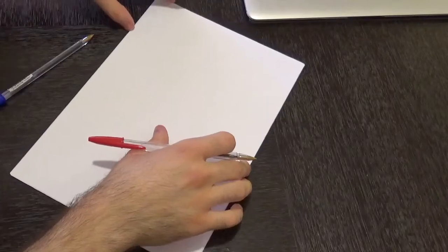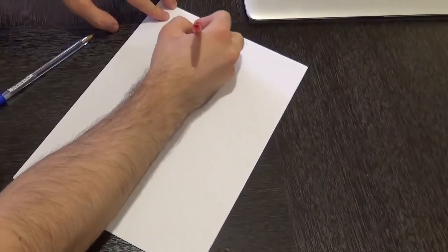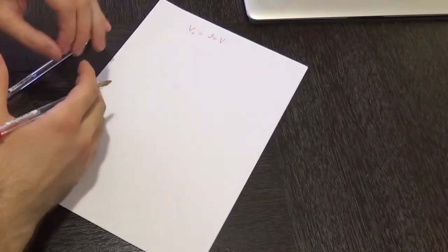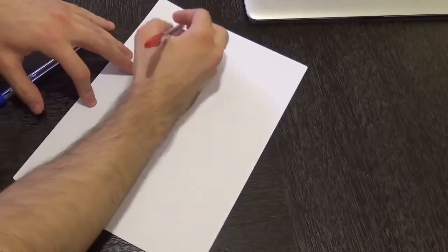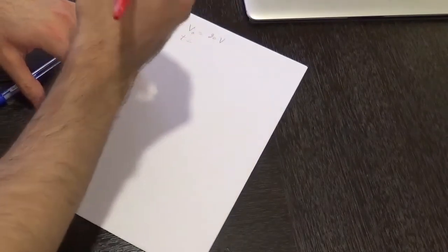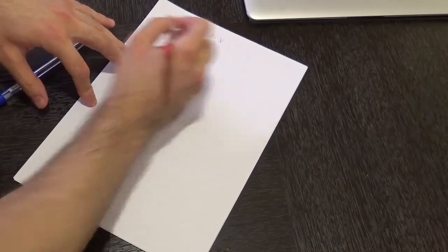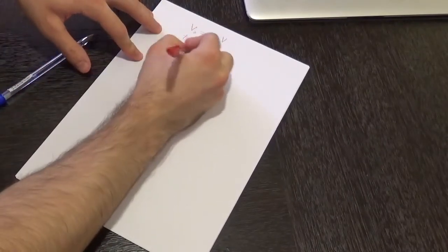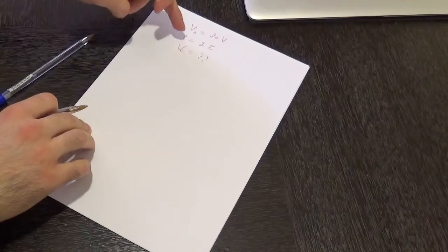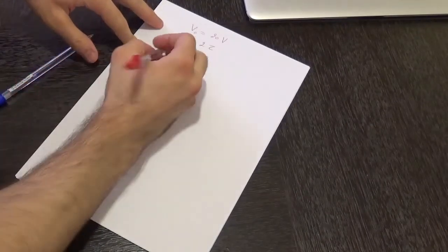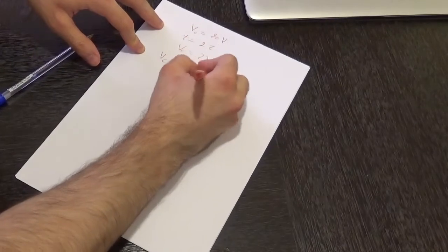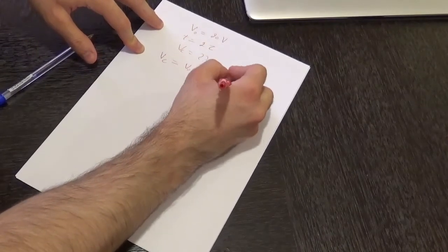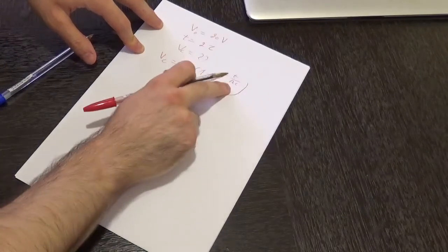Now let's consider that the battery is supplying the RC circuit with a voltage of 20 volts. And we want to determine the voltage across the capacitor after a time of t equal to 2 tau. In that case we have the following equation: Vc equal to V0 into 1 minus exponential minus t over RC, and RC in that case would be none other than tau.